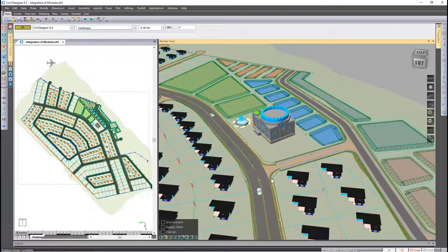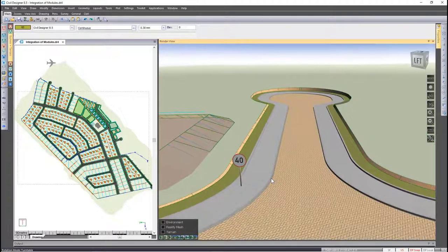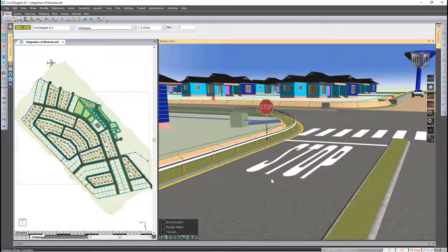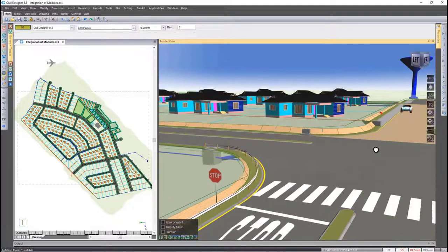I will start off with the shading order of multiple perimeter terraces on one surface. Surfaces in 8.5 can now be shaded in numerical order. This puts you in control of how these terraces are displayed. I will be announcing an exciting new road signage module for custom road entities, where if you insert road signs, markings, and linear road furniture, these entities will dynamically update as you make changes to your design. We'll also take a look at specifying unit lengths of curbs for IFC export and display purposes.